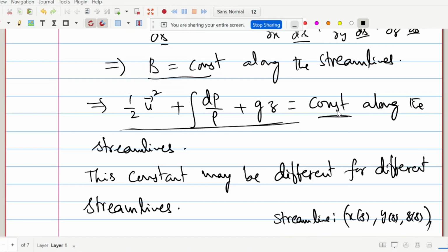But generally what we do is, if you calculate U from the other equations, del dot U equal to 0, dou rho by dou T, from there also you can get U. So U and rho you can calculate, and this may give you P in terms of U. I'm talking about the equation for incompressible fluids only, though this equation is valid for compressible also. Once you know the flow of the problem, you can get P directly from this.